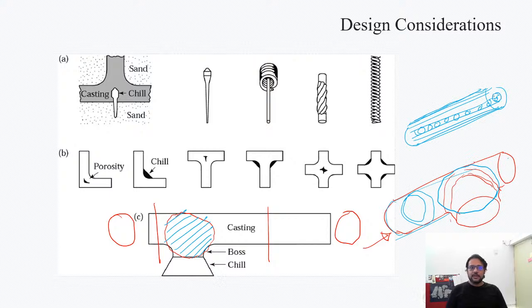Why it would cool this way, if you ask: take a certain time after it has started cooling. The temperature difference between the surface and the environment, let's say this is 30 degrees and this one is, let's say, 1500 degrees. You can imagine the temperature difference, it's huge. And so this temperature difference enables the loss of heat from the surface at a much higher rate.